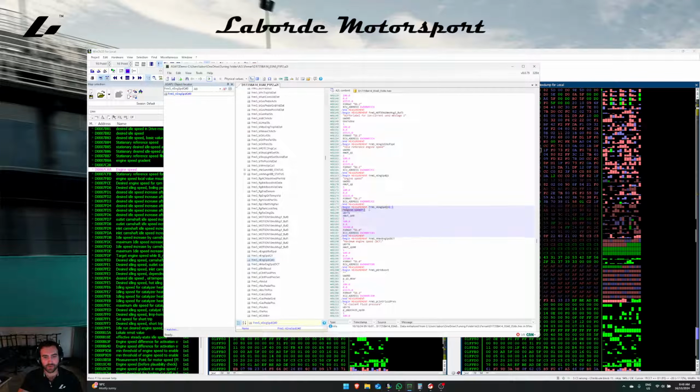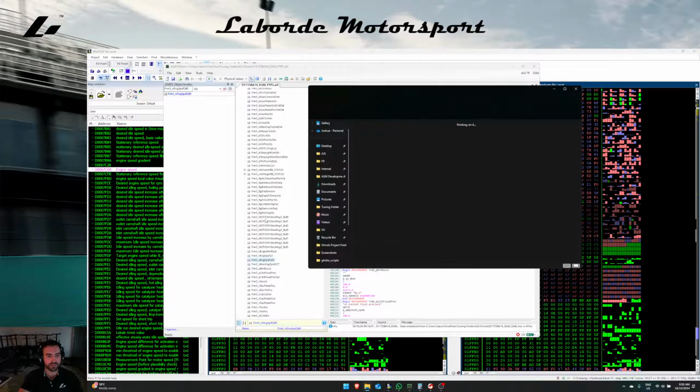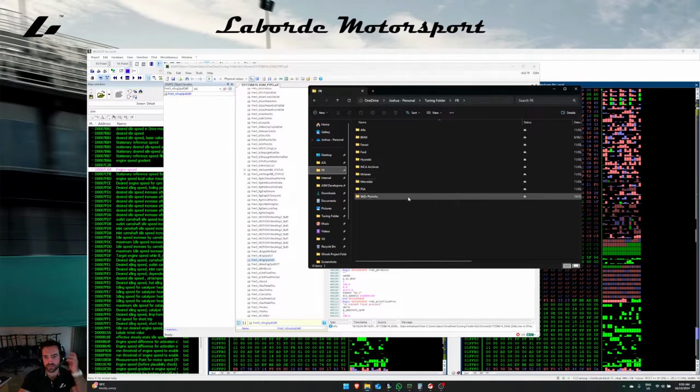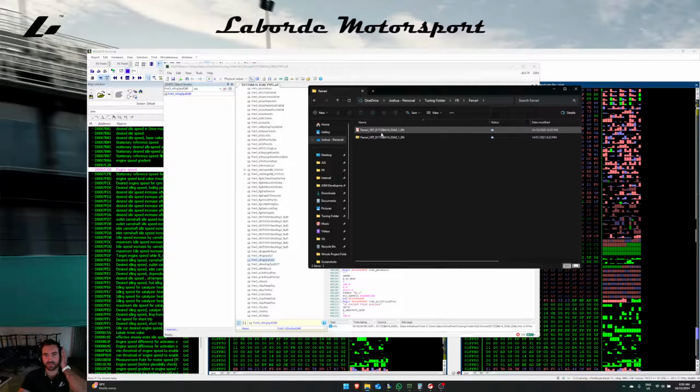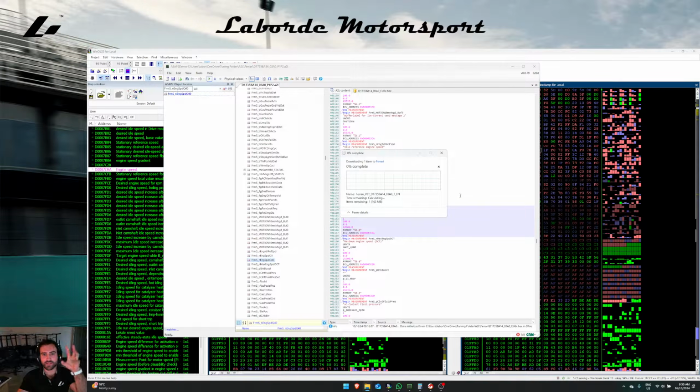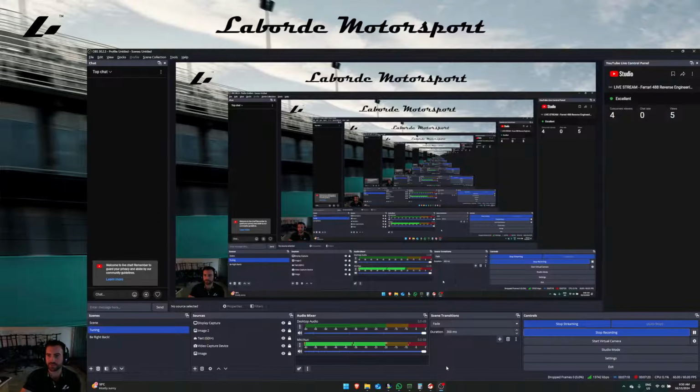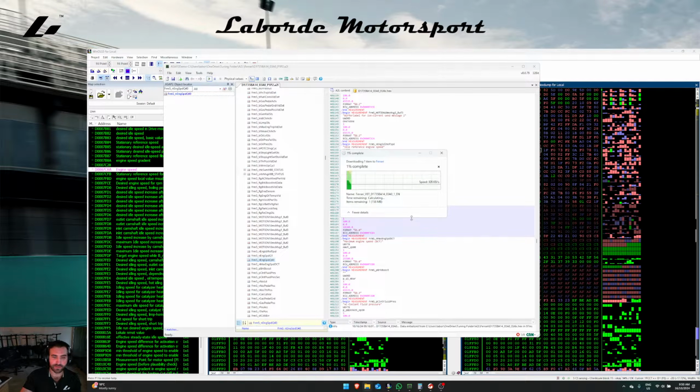So I'm going to go ahead, copy this, and we're going to go into our function sheets and try and find an example of the logic that's used with this. I probably have to download the function sheet because a lot of the stuff is on a drive. So once this downloads, I'll be able to go through the module where that particular variable is used and see how the logic is all interconnected and see whether or not it is a likely variable for the engine speed that's sent over the CAN to the cluster.